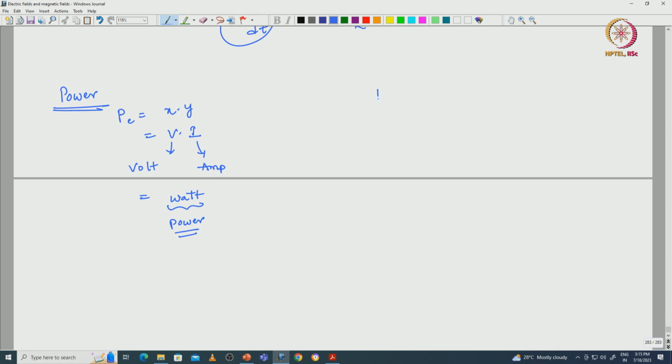And in thermal domain, effort variable times flow variable will give the power. Effort variable is change in temperature, and flow variable is dS by dt, change in entropy with respect to the time. So effort variable units are degree Celsius or Kelvin, and entropy change with respect to the time units are watt per degree Celsius. It will give again watt.